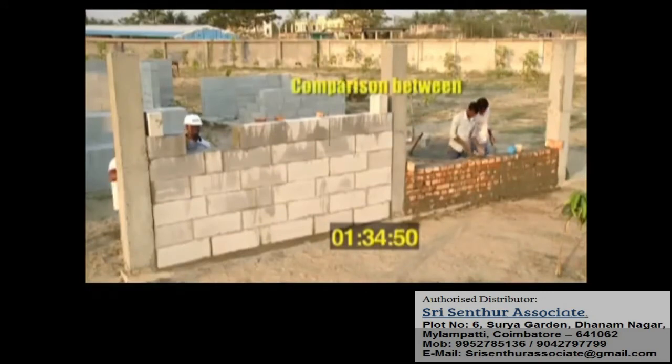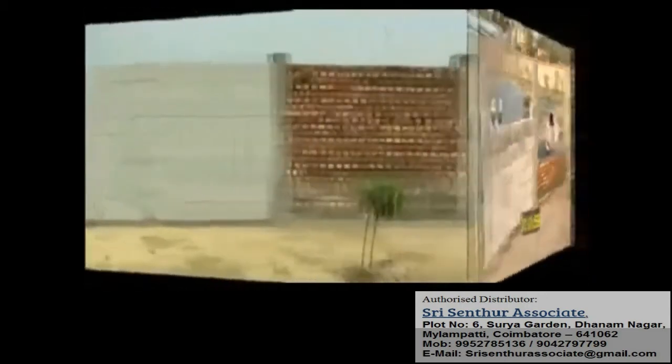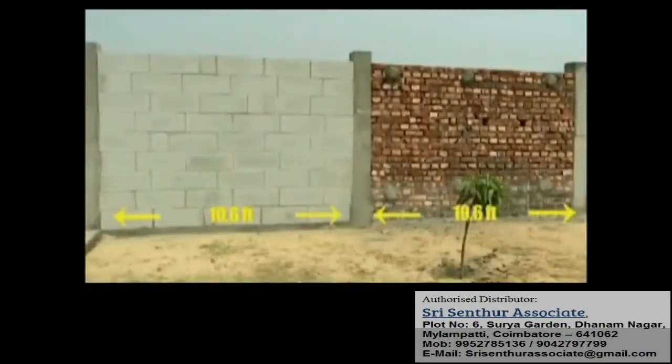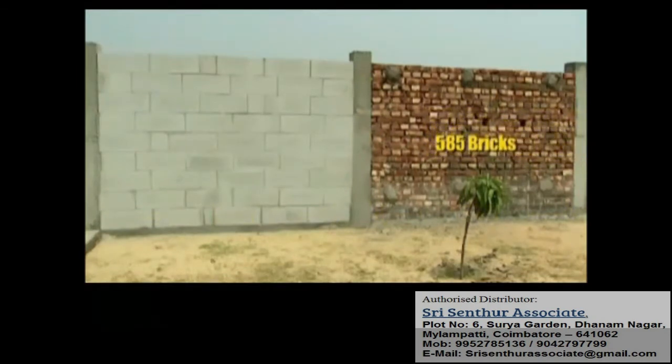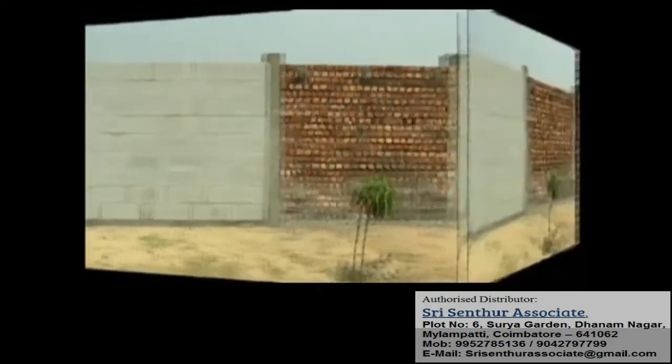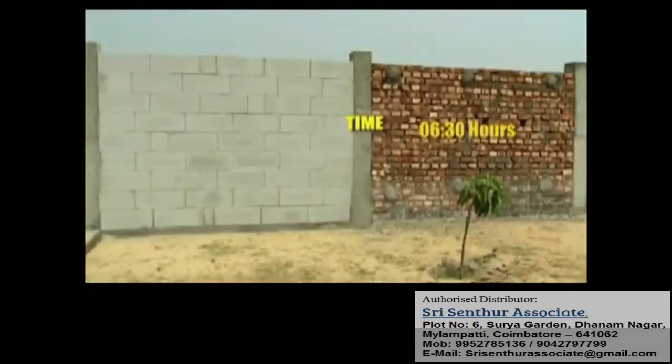Let us now study the comparison between AAC blocks and red clay bricks. To fill an area from pillar to pillar of 10.5 feet by 8 feet, 585 bricks were used, whereas, amazingly, only 50 blocks were used to fill the same area. The time taken for erecting the brick wall was 6.5 hours, whereas the blocks clocked at 3 hours only.